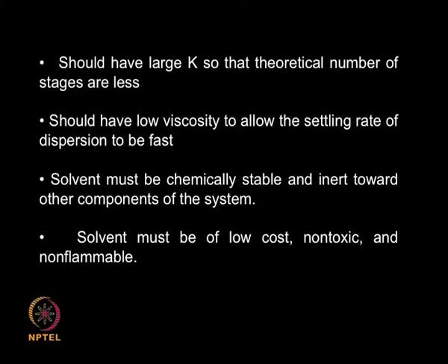Viscosity, if the viscosity is very large, then your settling is going to take much longer time. So, I should have low viscosity. Now, the solvent must be chemically stable. You do not want a solvent which is not chemically stable, it may start reacting with some of the solute molecules or feed molecules.